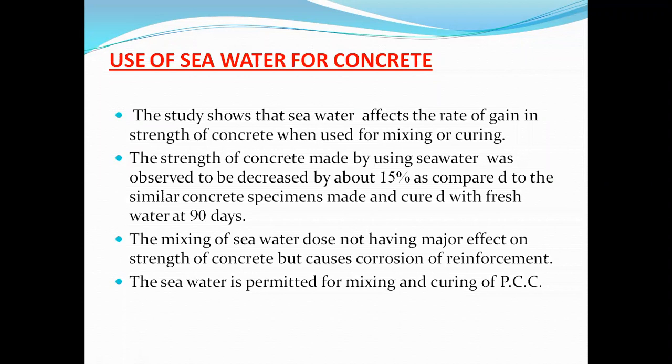Point number one is that studies show that seawater affects the rate of gain in strength of the concrete when used for mixing or curing. That is, when you use seawater for concreting or curing of a concrete, it will affect the rate of gain of the strength of the concrete. So we have to study or consider this effect of seawater on strength.